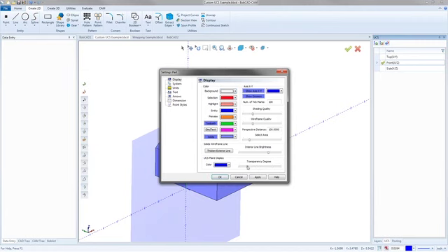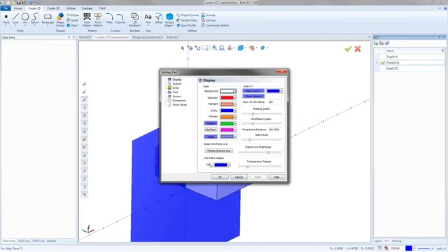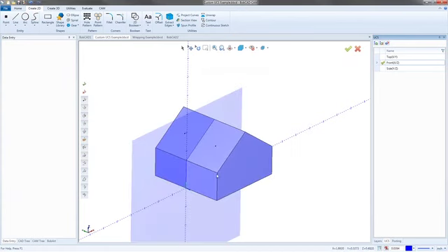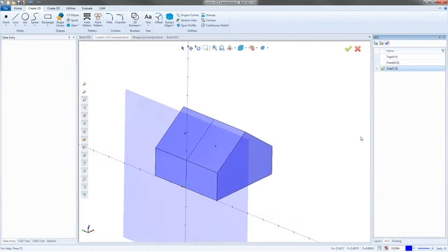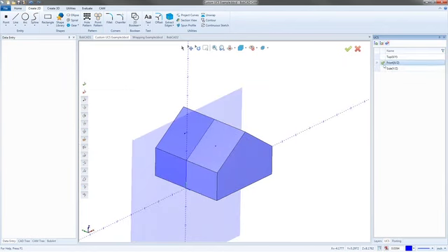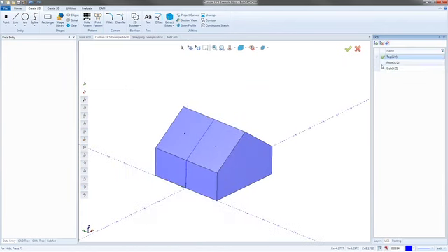If you bring it to the left, it will darken it up quite a bit, make it a lot harder to see through. So I'm going to leave it up about there. Looks good. Hit OK. And so again, that setting will only be taken on this one. So if I open up a new file and I make UCSs, it's going to go right back to the color I had it set to before. We also have that side plane UCS. So you got top, front, side. Now, depending on which one of these we are clicked on when we go into the UCS creation function, actually sets up some of the creation.